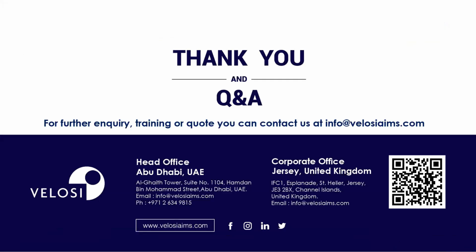Okay, there are a few questions. One question is, Gauri Shankar is asking, for example, if there was an extension of an existing building or modification, on what basis do you refine the life of the same building? It is a different question, because once there is an extension, it means you are putting in new loads or new effects. The whole building has to be redesigned technically, and then accordingly these factors are applied, and then life is extended for the older part.